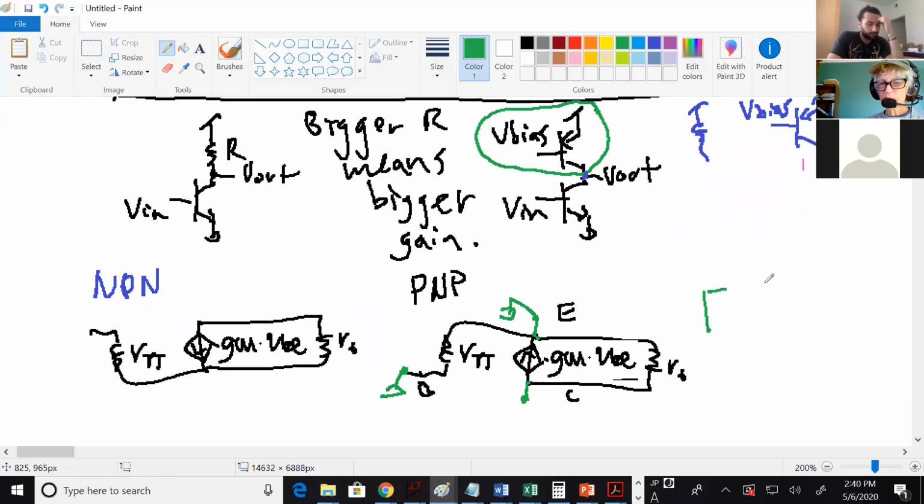So you have a black box here, and then the resistor in here, and you only have access to this point. Now it's on the bottom, but it's the same problem as when we were doing it for the NPN. So this would be your V test, and this would be your I test.